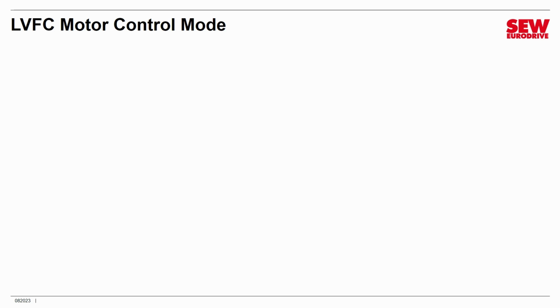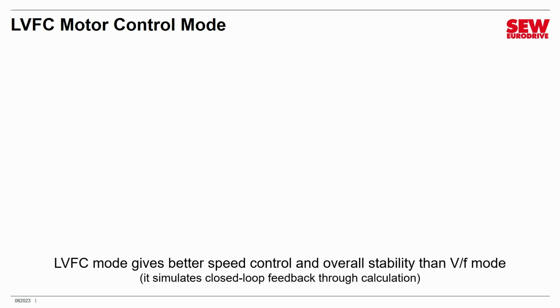By the way, it stands for Light Vector Flux Control. It is a more advanced mode that gives better speed control and generally better overall stability than VF mode. The way it does this, it simulates closed-loop feedback by calculating what the motor is doing. It is still an open-loop control system.